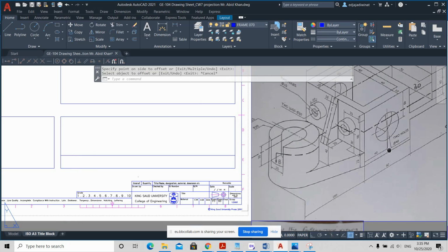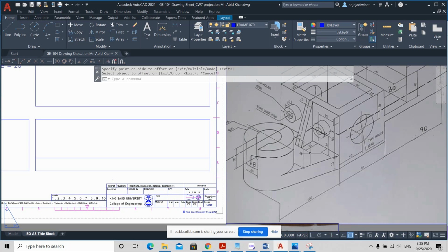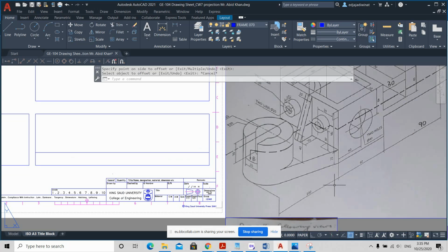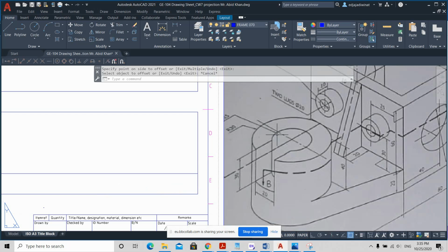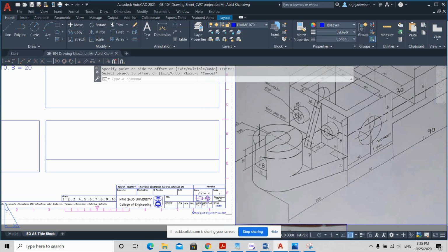let's find the easy thing to draw first. Okay, the distance here from here to the edge is 100, and the radius here is 15. Okay, 15 is the small one, 30 is the bigger one, so I think we can draw this. If we imagine that this is a cylinder with radius of 30, that means that edge will have a distance 60 from here, right?